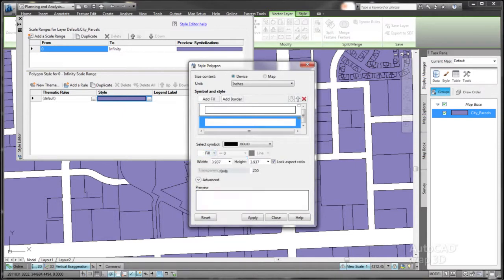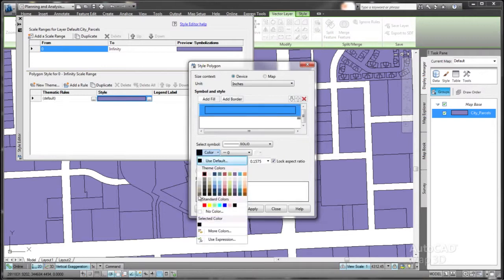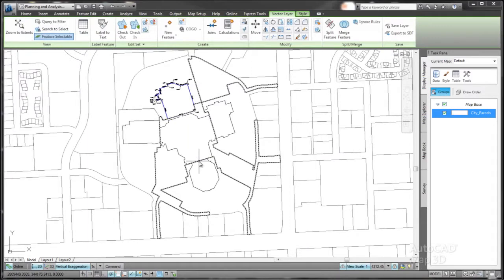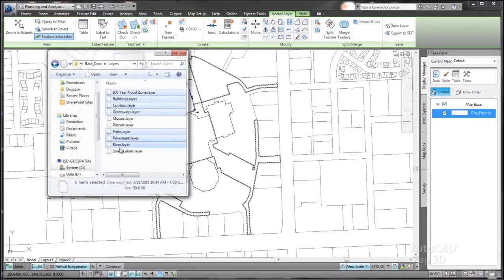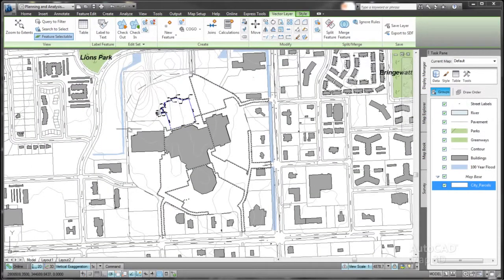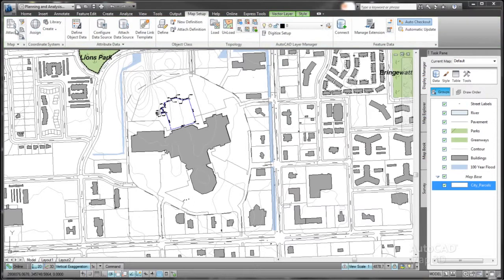information available as an ESRI SHP file from the local assessor's office. After stylizing the parcel, bring in additional GIS data such as hydrology, current surface contours generated from a point cloud captured for this project, flood zones, and both natural and built-up areas around the current project site.